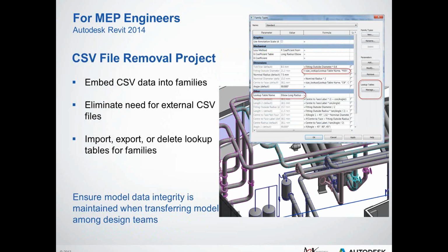Somewhat of an improvement in the family editing for MEP users. Lookup tables in the past have been a little bit of a problem in that when you create a lookup table for a fitting, you had to send that lookup table to other people, or you had to maybe configure it for other users and so on.